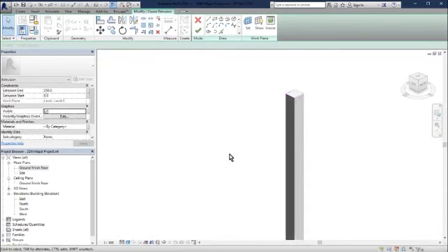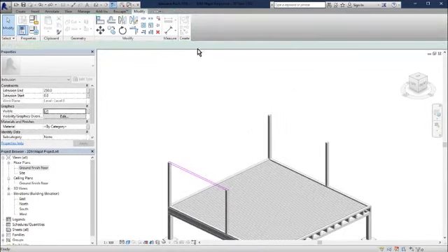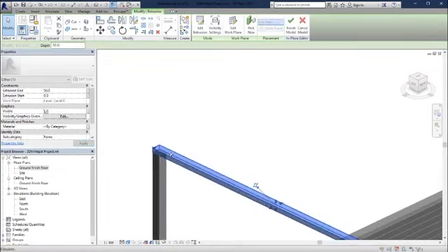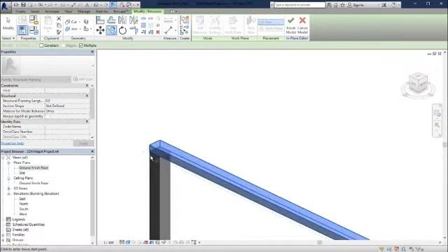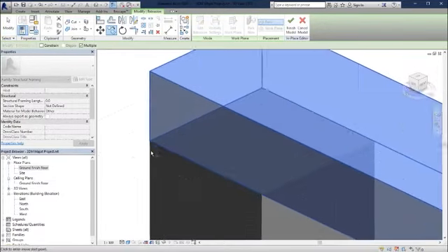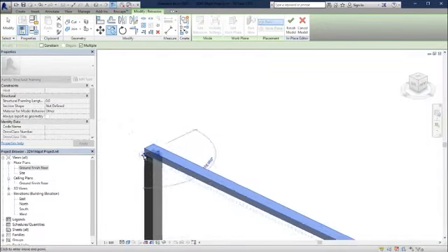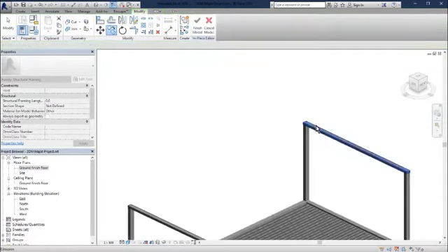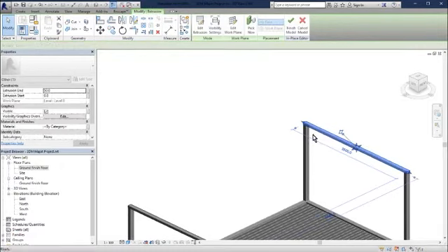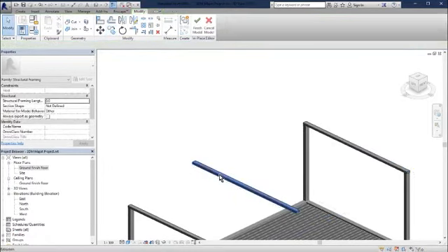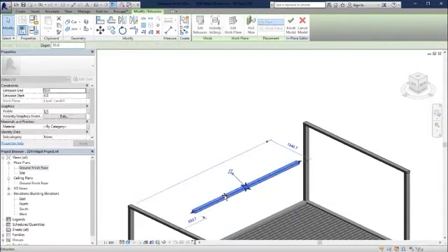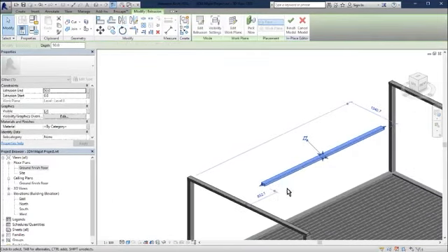So we're going to actually undo that, and we're going to create one, and this is going to be 50 millimeters tall. And we're going to copy this. Here, so we actually need to build it first, and then we copy it. We're going to rotate this 90 degrees,